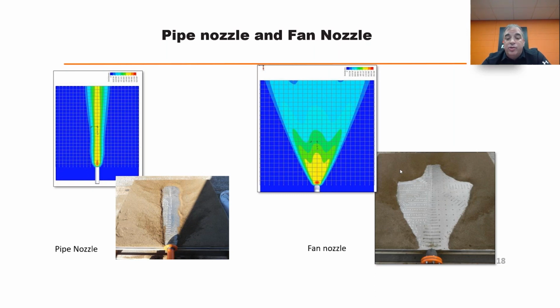If you use fan nozzles, you can put 2 cannons and 2 fan nozzles, where it would take 3 cannons and 3 pipes to clean that same area. So it reduces the amount of air cannons needed, and it cleans more efficiently.